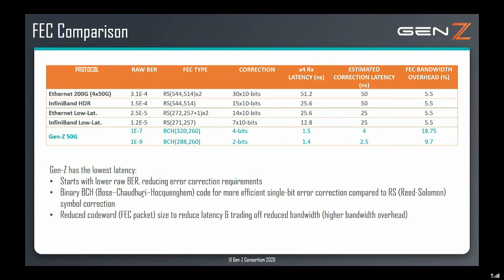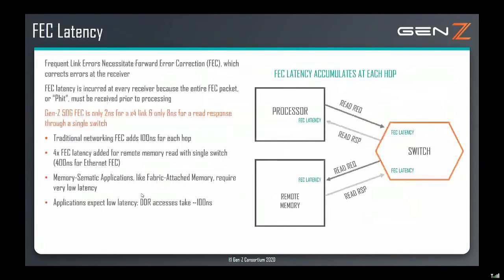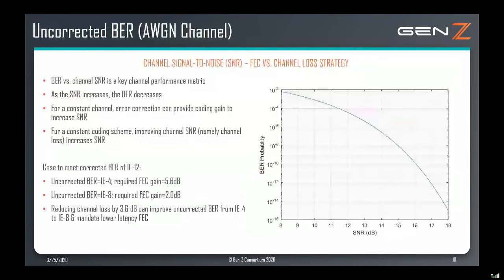These curves would actually be protocol agnostic. They are in fact just bits being sent through an additive white Gaussian noise channel. One might also ask the question, what about NRZ versus PAM4? As per what James mentioned, since we're looking at very infrequent errors, this was for illustrative purposes of showing the trade-off of a better SNR baseline versus a bit error rate, more so than decomposing, let's say, frame loss or coding, et cetera. So these curves are protocol agnostic.